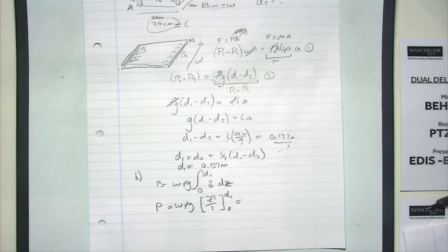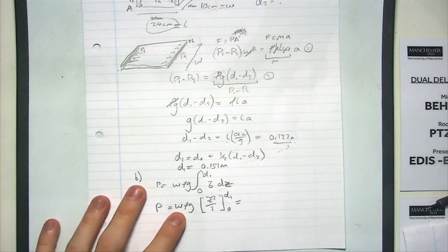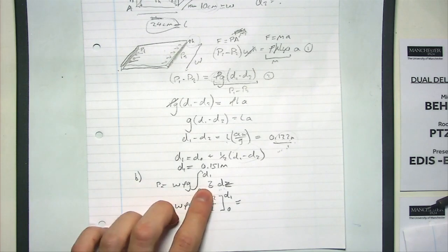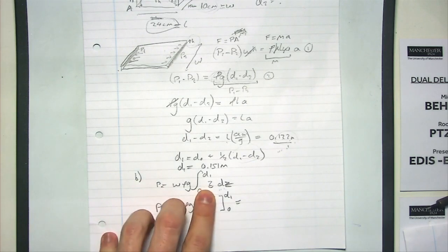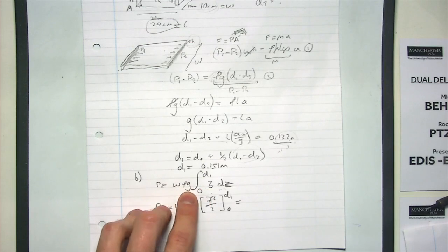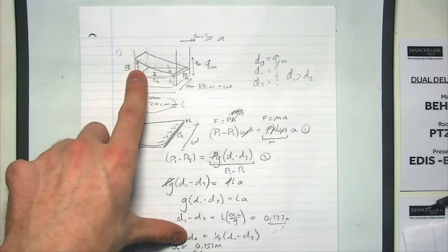and then what's the pressure on that? Tiny little slice, what's the pressure on that? And that pressure changes at each part of the depth, because as we go deeper, there's more fluid on top of us. So that pressure is variable, there's a gradient to it, okay? So all we're saying with the integral is add up all those tiny little differences, and that gives us our full pressure force, okay? So that's what that says. Are we happy with that? Yes? We use g, not a, because we're just analyzing it vertically, because we're talking about the weight of the fluid.